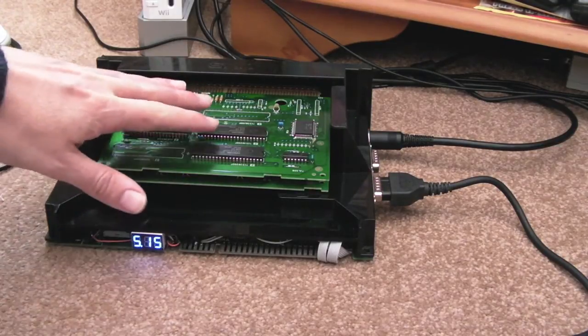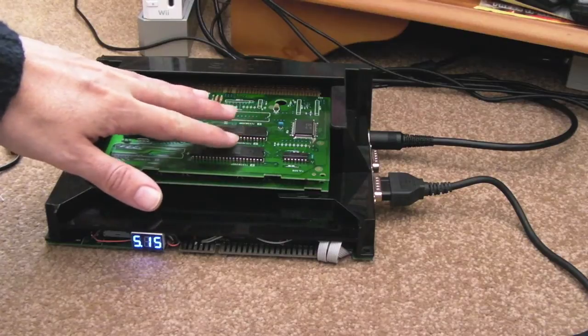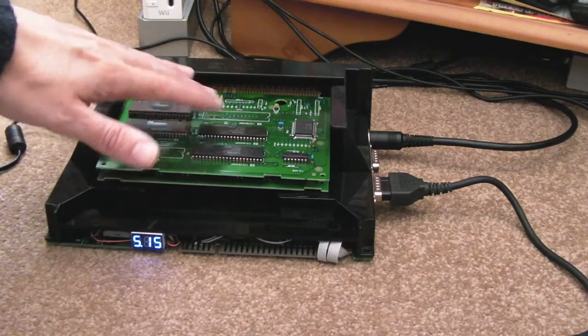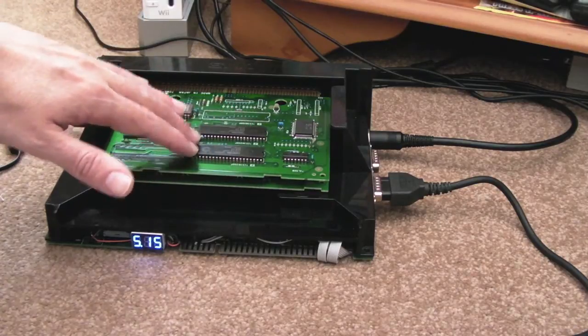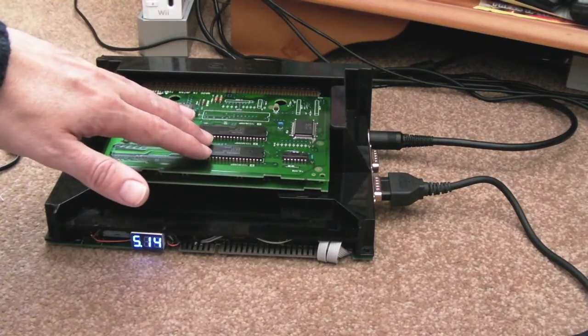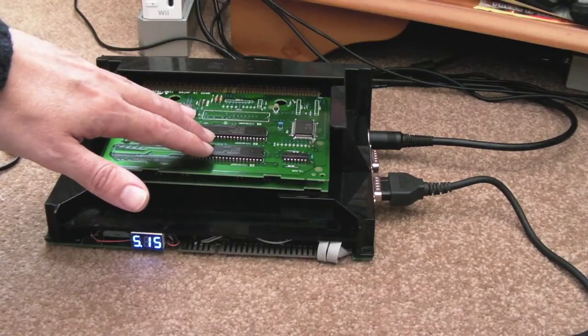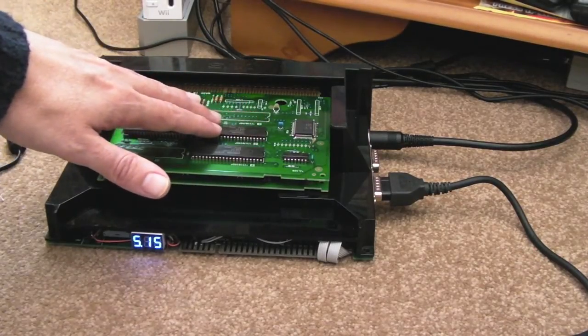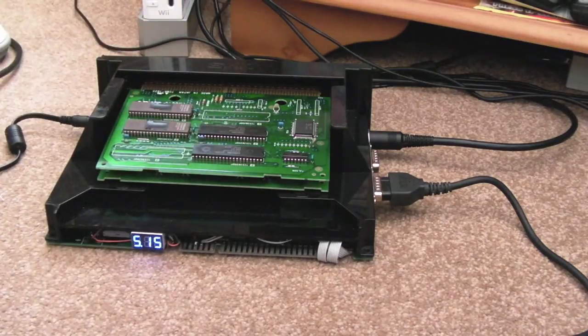The other thing that goes hand in hand with that diagnosis is the fact there's 2 of these chips. So obviously at some point it's going to be taking samples from one chip. That chip might be completely dodgy, with all the samples corrupted, or many of them, but then you would expect some really clear samples to come back from the other one at some point. So you'd still expect it to be intermittent, and that is not what's happening here.